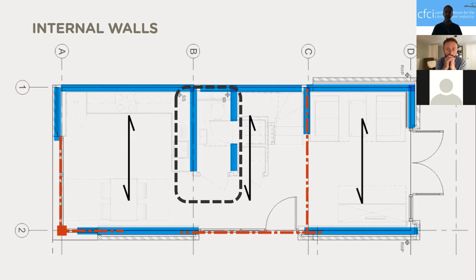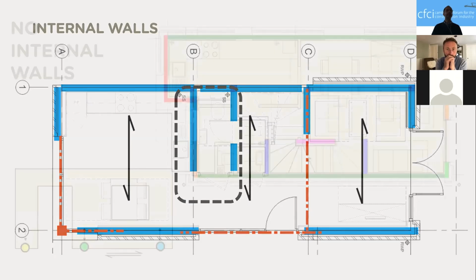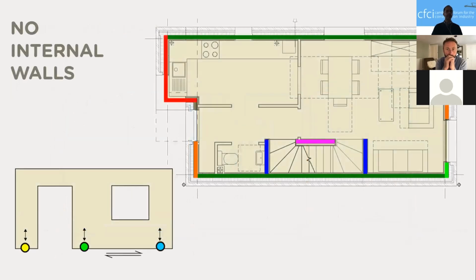If we're not trying to do things internally, it also restricts the freedom of the space. So we spent a lot of time with the client evaluating things and coming up with systems that free up the need for access hatches and holding things down, by using a heavier facade, thicker CLT facades, to act as a portal frame of sorts and provide that stability.